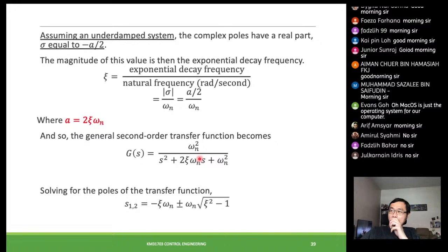Whereas the 4ac, when you do this, actually becomes 1. Immediately you can solve it by looking at the damping ratio and the natural frequency, and from that onwards it would be much easier for us to describe the damping. Now we only look at the damping ratio.